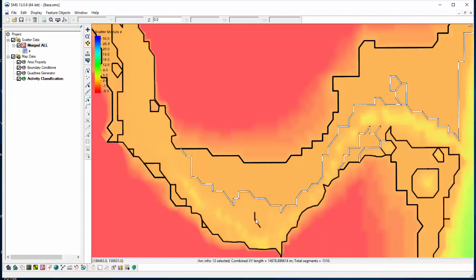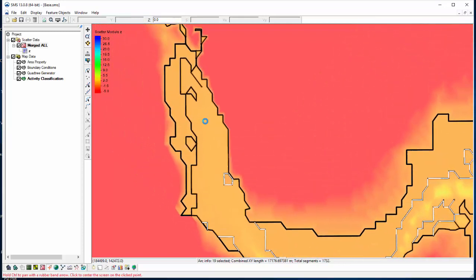And so I'm going to keep working. I'm not going to do this for very long, but I just wanted to give you a good idea. All right, and I mentioned earlier that if you wanted to pan, you can let up off your shift key, hold down your F2 key, and your cursor now becomes a hand instead of a pointer, and you can drag and change this. So now back with the shift key, I'll go back and delete a few other things.